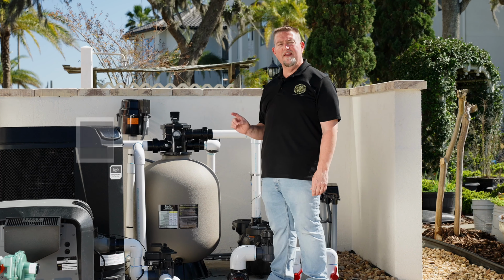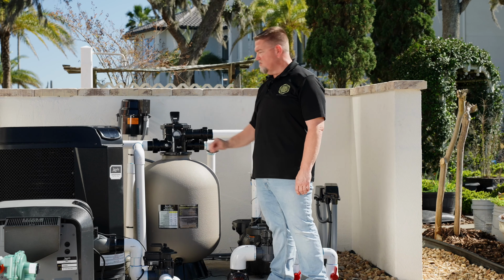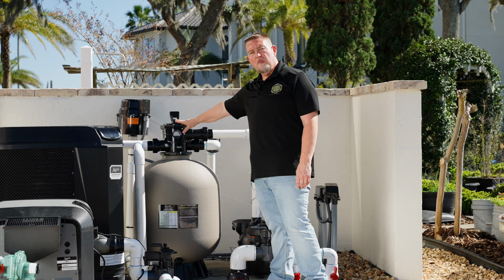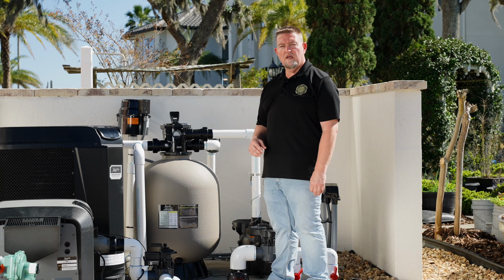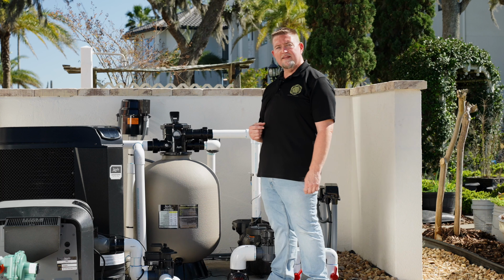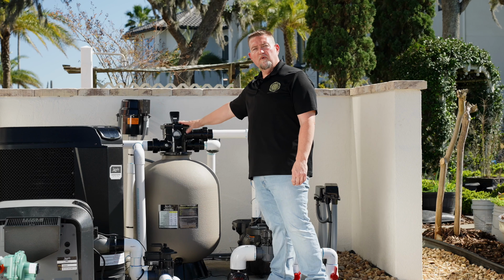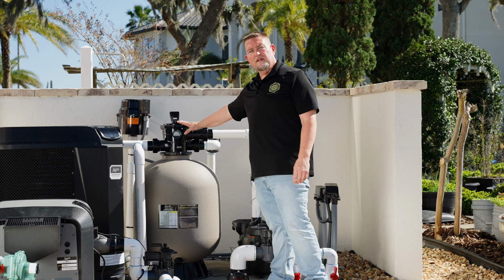First and foremost, never turn the valve while the system's on. Always shut the system off first before rotating this valve. The other thing to remember is always rotate clockwise, not counterclockwise. There's a baffle on the inside of the valve that potentially could grab the gasket, causing a tear and creating problems for your system. So always remember, system off first, rotate clockwise.